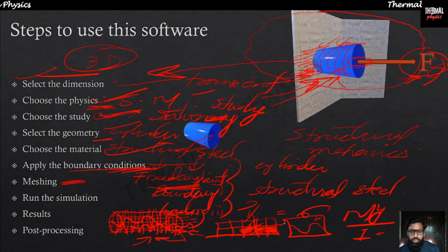So if the meshing is coarser, if the mesh element we have chosen is larger, it will consider that the stress is uniform in this larger element, and then it is changing from this element to the next element. But actually stress gradients are very large, so it is changing within each element also.